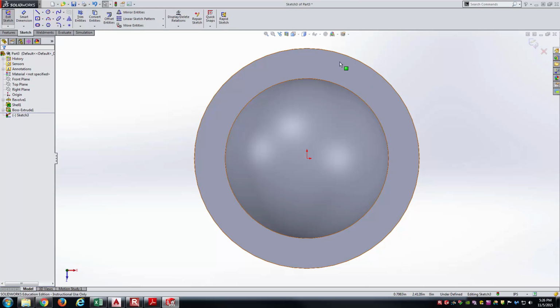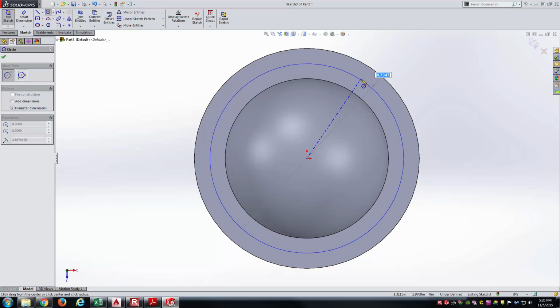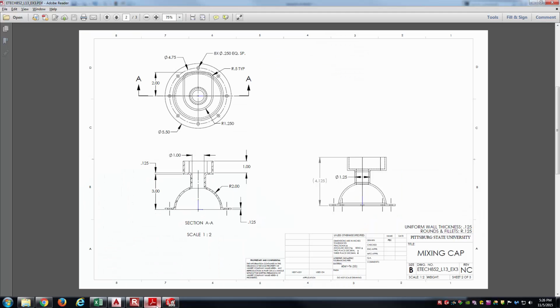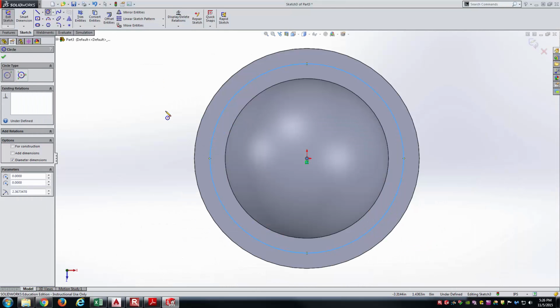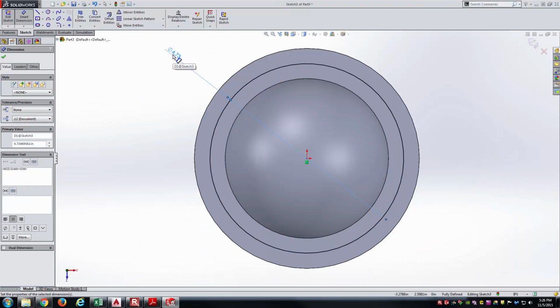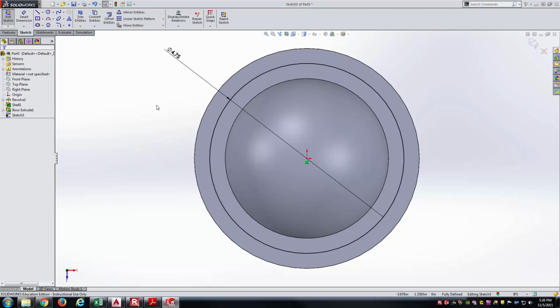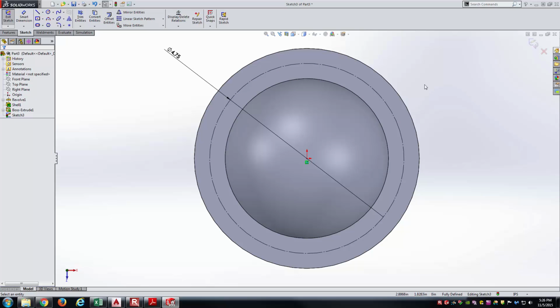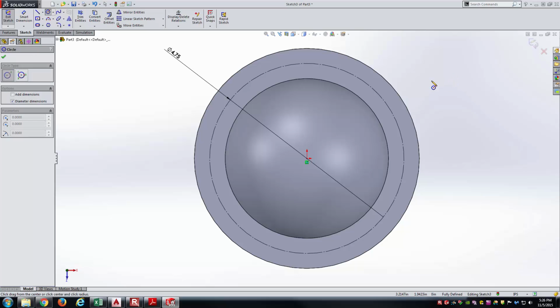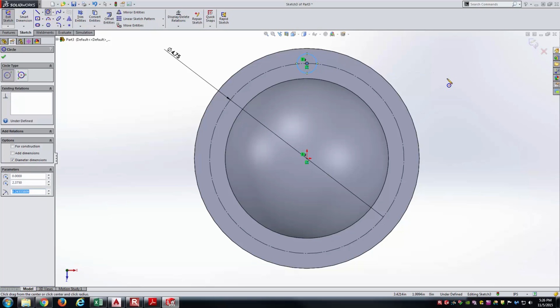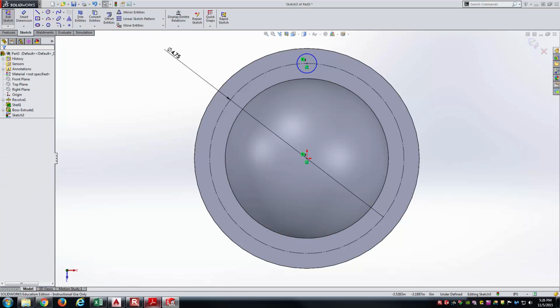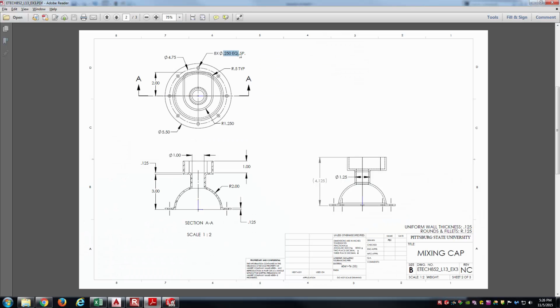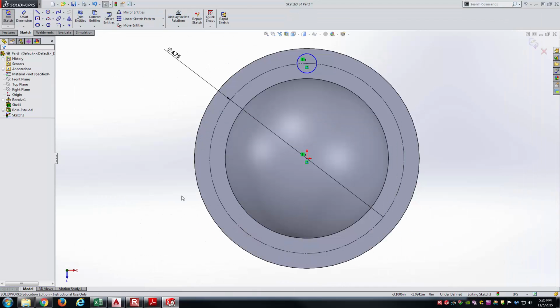I'll get a sketch going on that top face, as you saw. It's on some bolt circle here, so I can define the bolt circle diameter. Looks like it's 4.75 right from the top view. Just drawing the circle, 4.75 inches for the diameter. The center point of the circle is right at the origin, and I'm going to make it construction as well, because I'm not really needing it to define the boundary of the cut extrude. Right at the top of this circle, I can snap to that quadrant position, center my circle for my hole, and it is a diameter of 0.25, so 1/4 inch diameter.